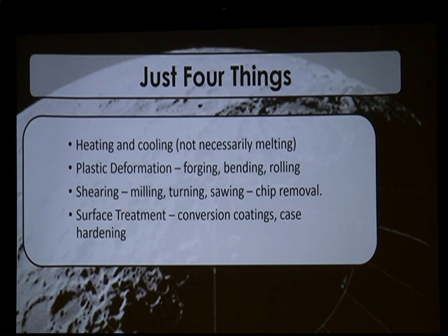As a blacksmith working with carbon steel, it's really simple. I've got iron and carbon, and there's a couple of temperatures where the phases change of the material, not from solid to liquid, but just the arrangement of the molecules inside, ratio of carbon and iron in each grain. If I take it above critical and just dunk it in a bucket of water and cool it rapidly, then I have probably the hardest material that I can get with that particular alloy of steel.